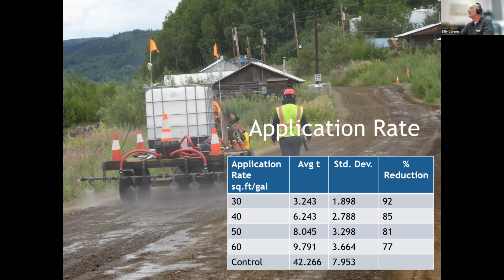How long will each application last? That really depends on your application, what your traffic is, whether you've got curves or a steep grade. Most of our villages, we're going to get most of the summer, and in some of the heavier traffic villages, you may have to apply it twice. On an airport, we typically get about 2 years out of it.